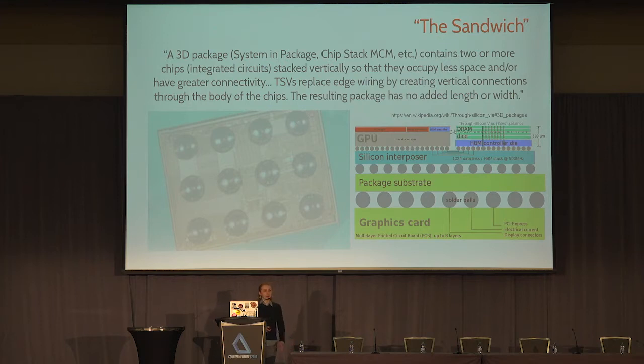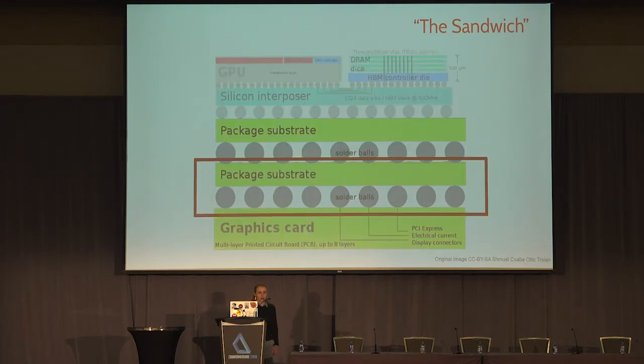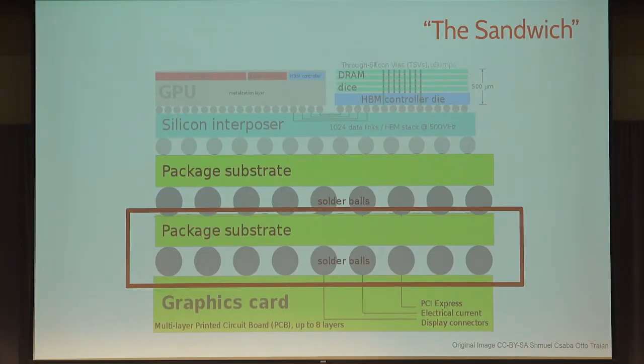So it sounds great, right? But from a security standpoint, an issue with this is that you really can't see everything that's going on. Some of these vias might differ, and the differences in where vias are placed might affect certain initial security components of the chip, or might actually connect a completely different chip that's hidden in the sandwich. For example, something could be hidden right here that you wouldn't see at the surface layer.